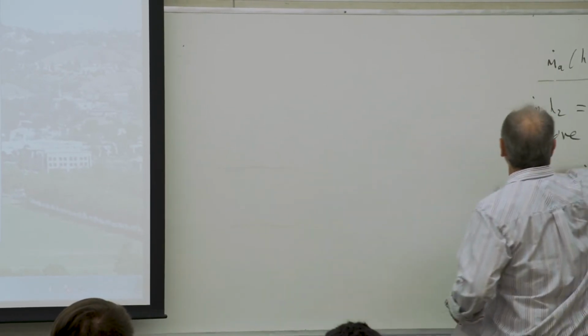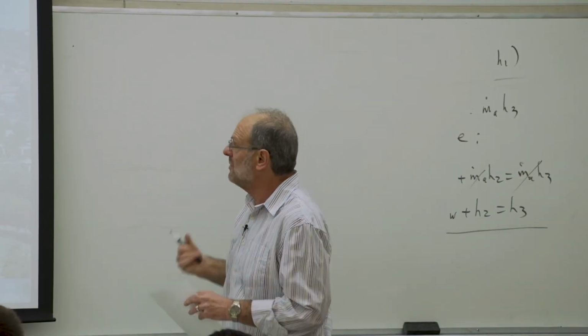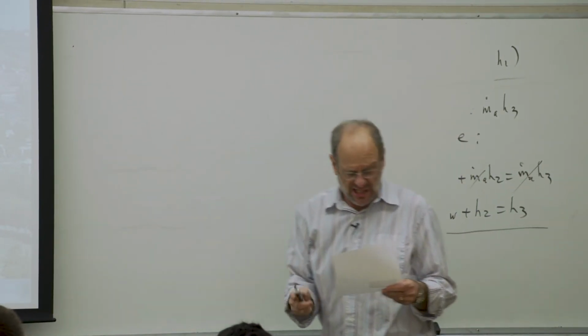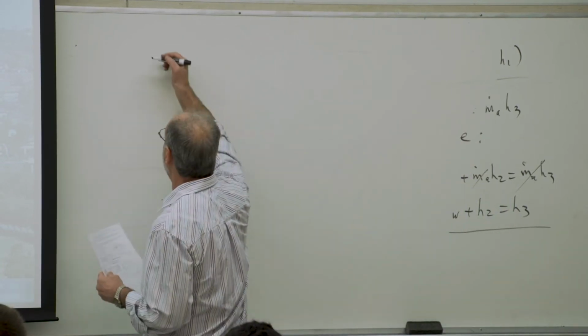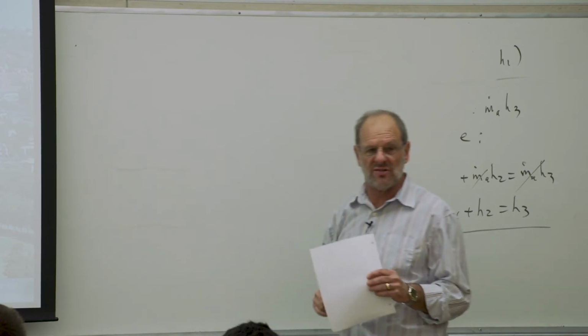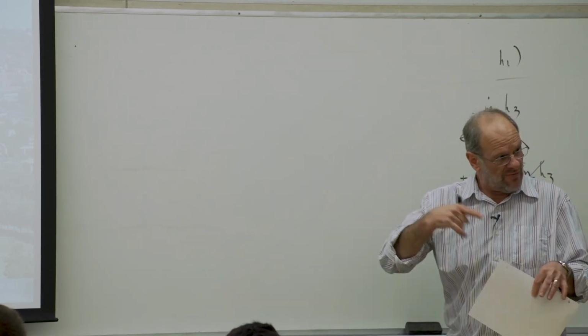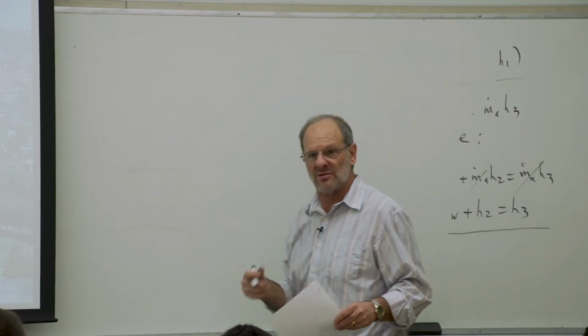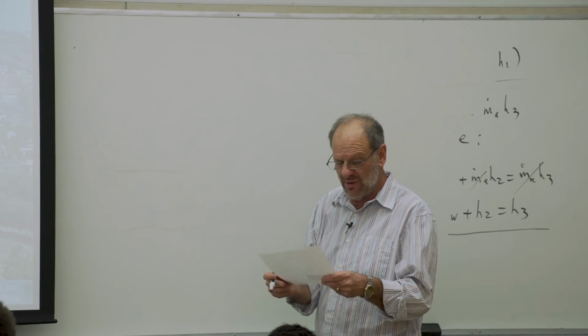First of all, let's identify all the data that's been given. Even though, at least in my mind, it's pretty clear what we have, it's not always real clear. The fact that it says air at 14.7 psia is the author's way of saying you can use a psychrometric chart, our 14.7 psia psychrometric chart, which is figure A31E way in the back of your book.